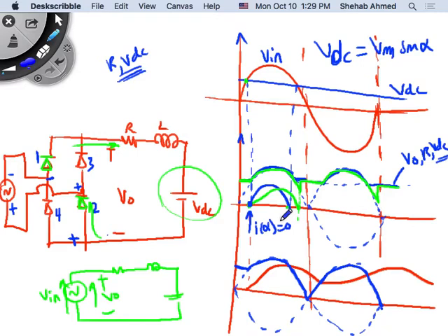In your equation for current, you have a forced response and a natural response, exactly the same as the chapter 3 material. Then you have a variable A that you find from initial conditions. If you want to find your average output voltage, you have to find your current extinction point, which we call beta. How do you find beta? I of beta is equal to 0, and you find that numerically because you don't have a closed form. It's the same equation that we had in chapter 3. We just keep repeating it.